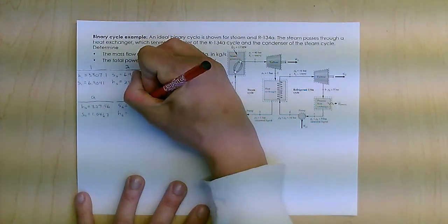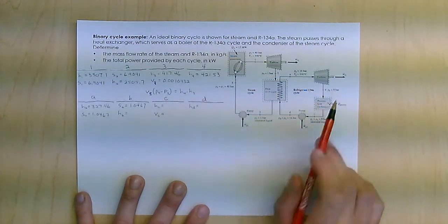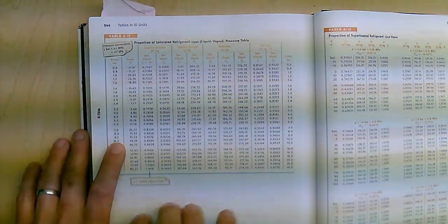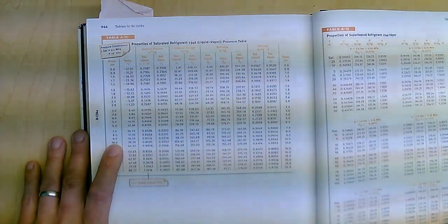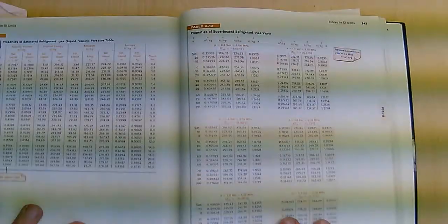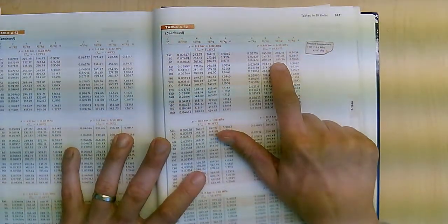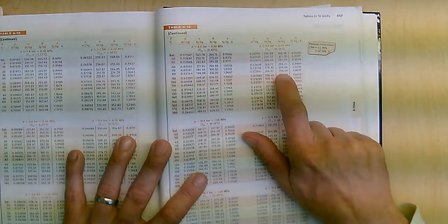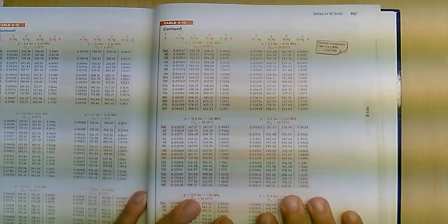Again, that turbine is also isentropic, so that S is constant. So SB is also 1.0467. Its pressure is 9 bar. So I'm going to come over here to saturation, 9 bar, and again my S was 1.04. I'm actually above that, so I need to go into these tables for 9 bar. I have 9 bar right here, and my S is 1.04, so I'm somewhere in between. You can do the interpolation, and I get 312.74.